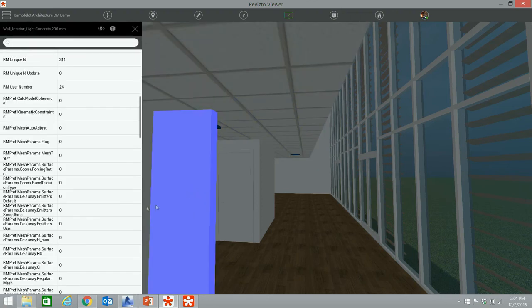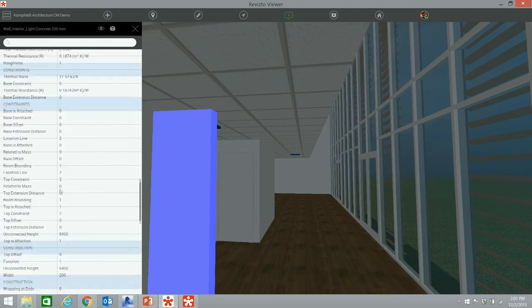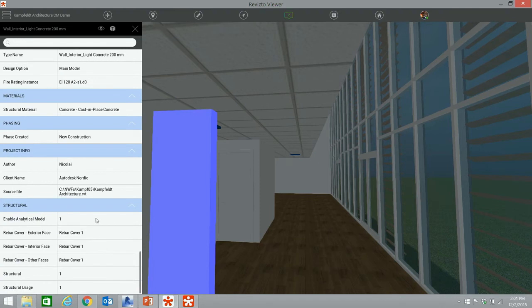By clicking on each object, you will see the whole data that you have attached in your Revit, and it's totally searchable. While I'm typing, it gives you the highlights, and it also shows you the name of the file and who created the file, because you have linked files created by different people. Here, by clicking, you can see who is the author of that particular object.